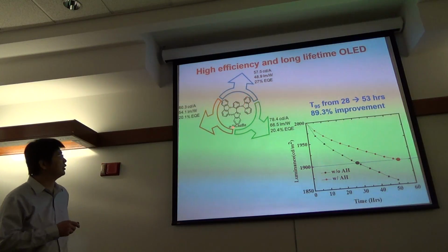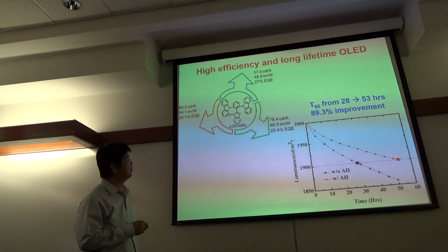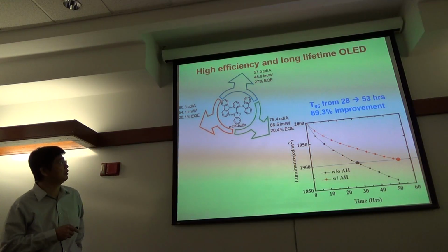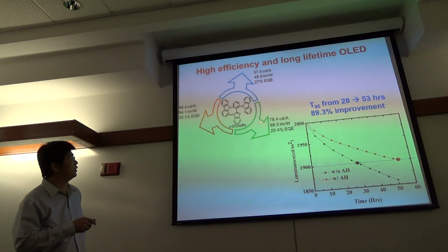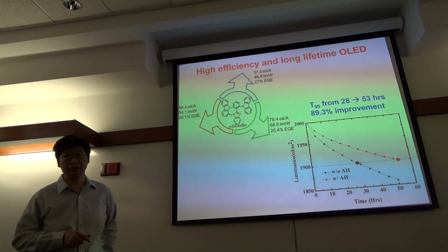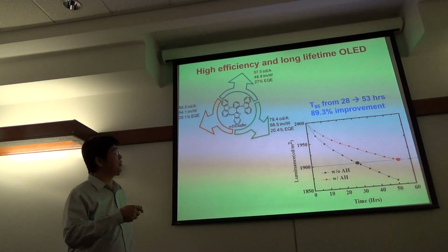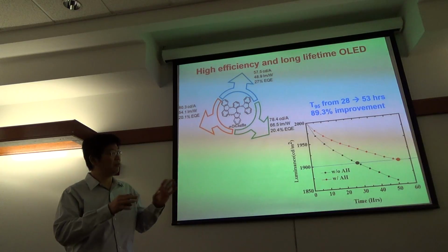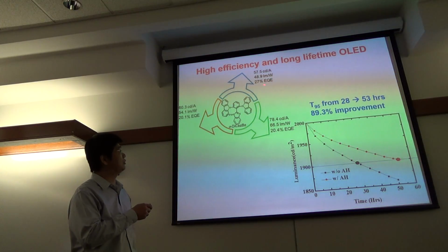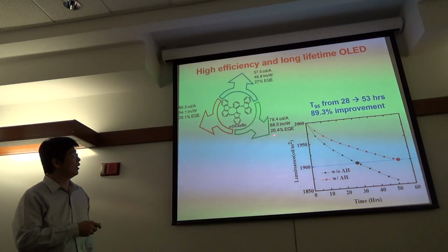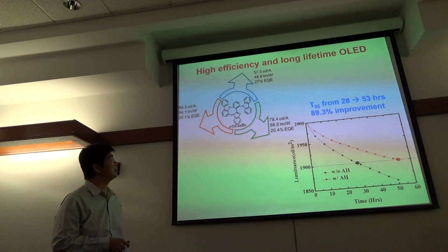One example is we collaborate with chemists, who have synthesized a universal host material, so we can fabricate blue, green, or red OLED. And as you know, typically there's an upper limit of roughly 20 to 30% in external quantum efficiency due to the total internal reflection. So actually, those values are pretty high, close to the theoretical limit.